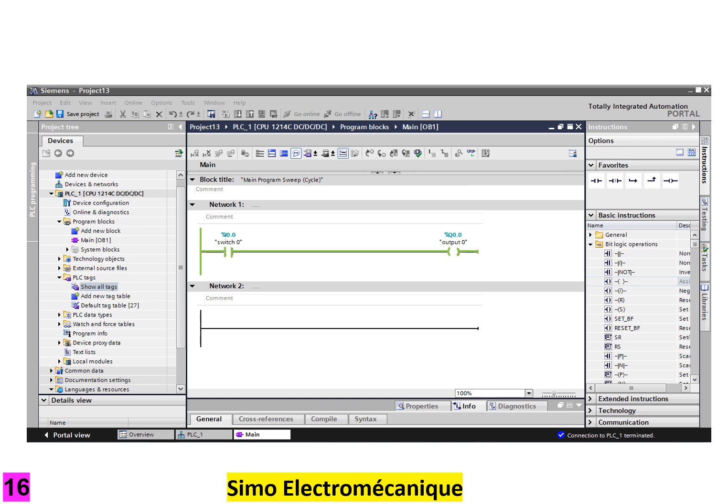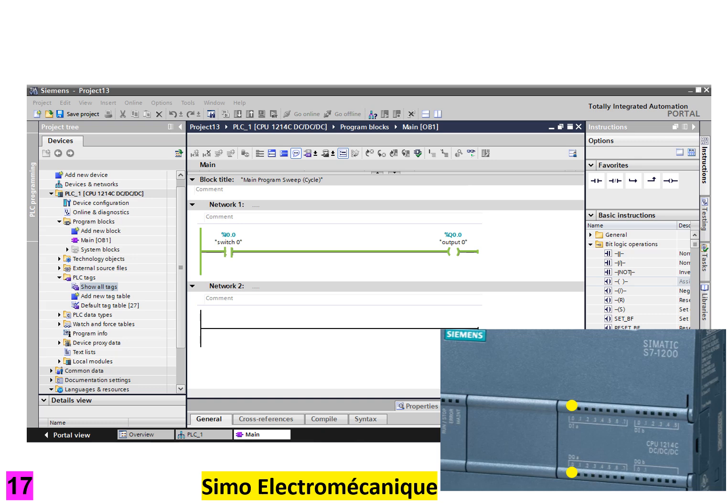We can toggle the input switch to see the effects in real time. Look at the inputs and outputs and you will see that output 0 will follow the state of input 0. Look at the inputs and outputs on the front of the PLC and you will see that output 0 will follow the state of input 0.